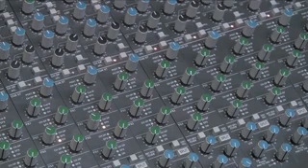External effects units normally receive a post-fader signal. When using effects sends as headphone cues, you would usually set the aux send to pre-fader in order to have an independent mix for the musicians.